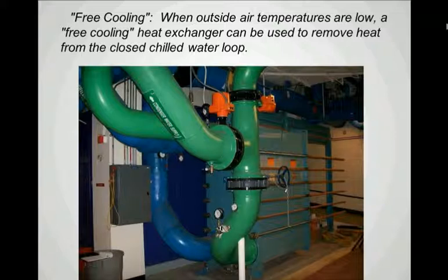Now here's a photograph of a free cooling heat exchanger. When outside air temperatures get low enough, and usually that's below 55 degrees, a free cooling heat exchanger can be used to remove heat from the closed chilled water loop.